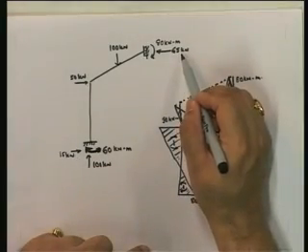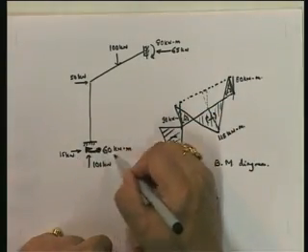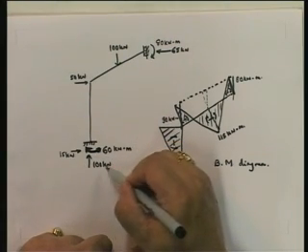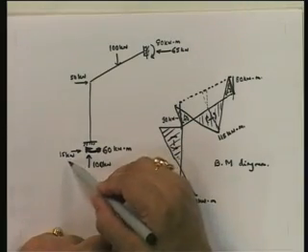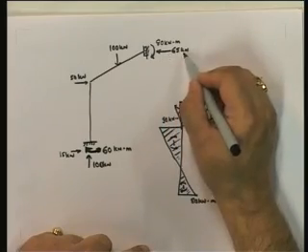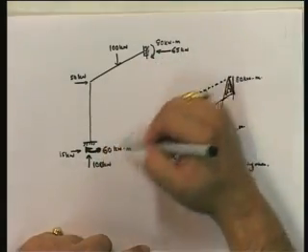Next is the solution. Last time I derived the expressions for how to get the support reactions. If you remember, 50 plus HA is equal to HC, and HA is equal to minus of MBA plus MAB upon 10. Substituting MBA and MAB into the expression for HA, we got that HA is equal to 15, therefore HC is equal to 65, and these are the support reactions. Clockwise moment of 60 kilonewton meter here, a vertical reaction of 100 kilonewtons, a horizontal reaction of 15 kilonewtons, and a horizontal reaction of 65 kilonewtons in this direction. These are the support reactions.